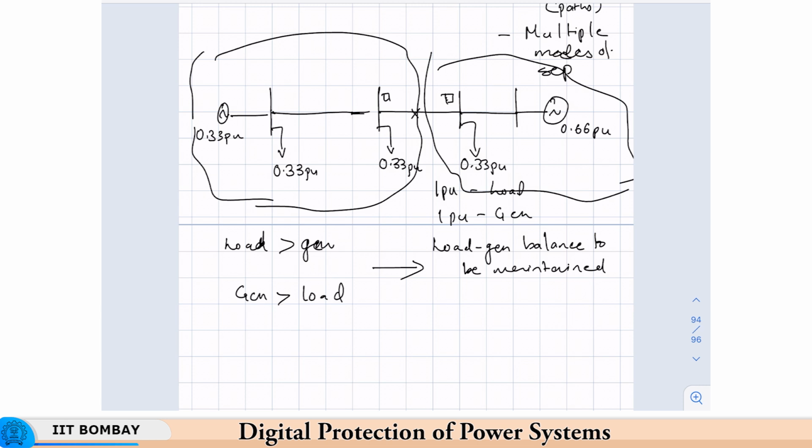So, here unless there is load shedding, stable operation will not be possible, and here the generator will have to be backed down, which is something we want to avoid. So, here you will have to shed one of these loads, and even then, because the swing has progressed too far, stable operation may not be possible. So, this you want to avoid.